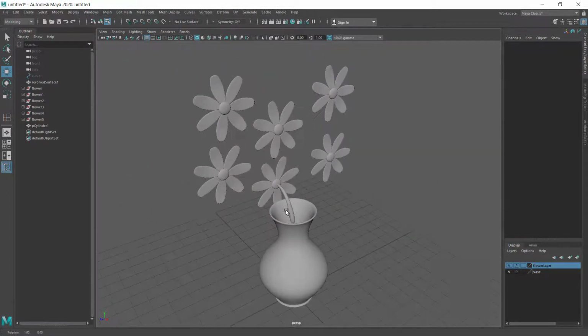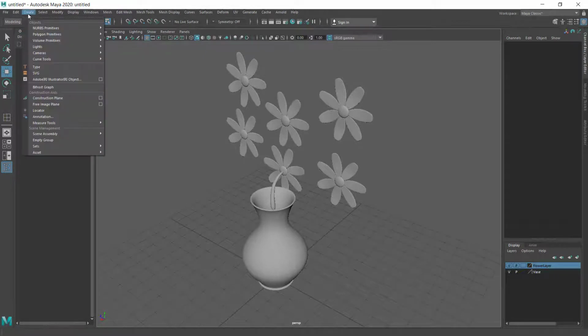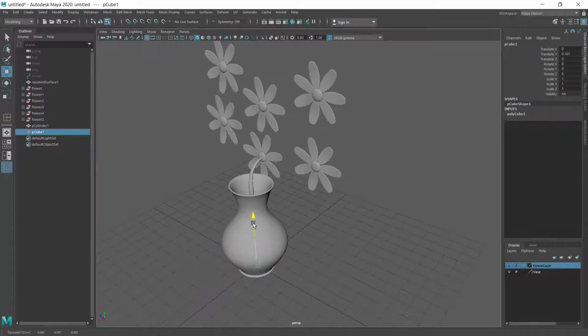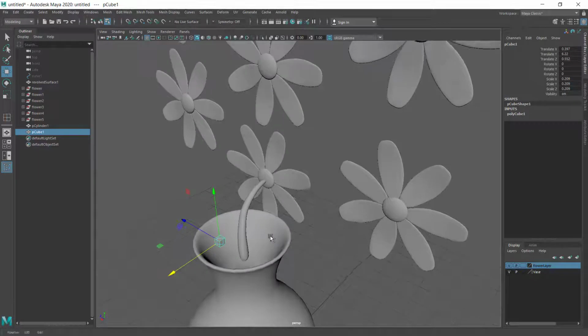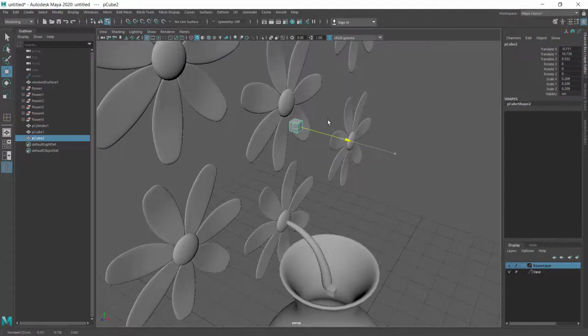Now let's do a little bit complicated method for this guy. This time I'm going to basically pick up, let's say a cube, and we can actually have a copy of that same cube to basically bridge the shape. So I'll just push this out a bit, okay, and I'm going to make a copy of that. Control D, then pull it up and then pull it over here.